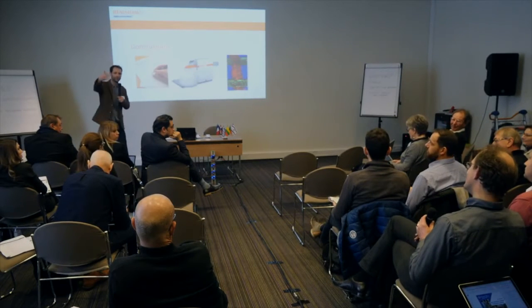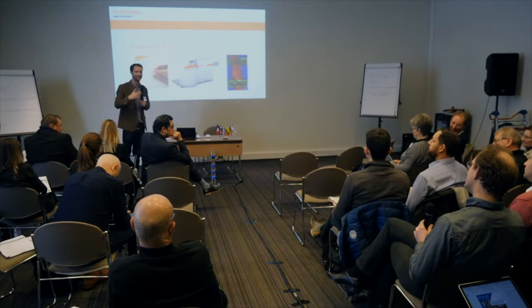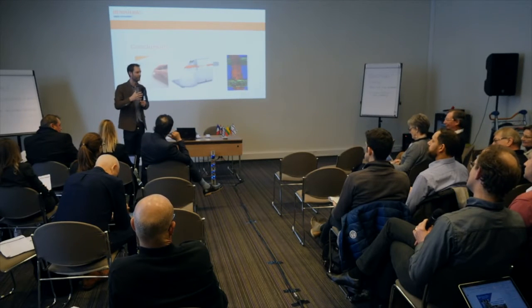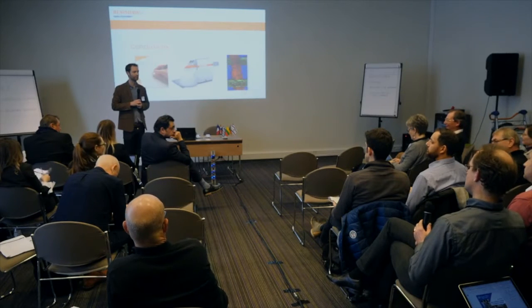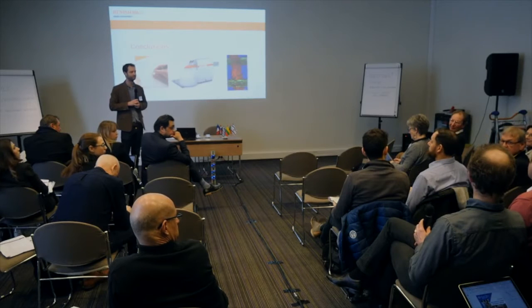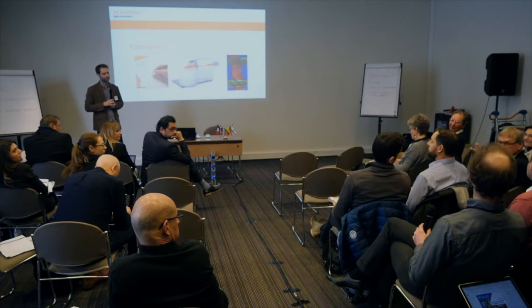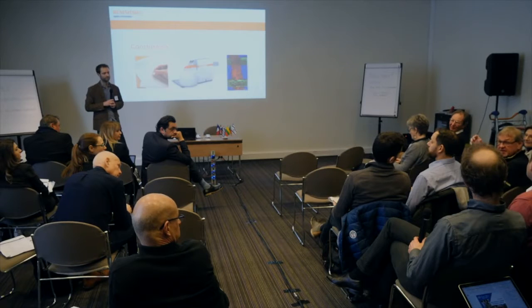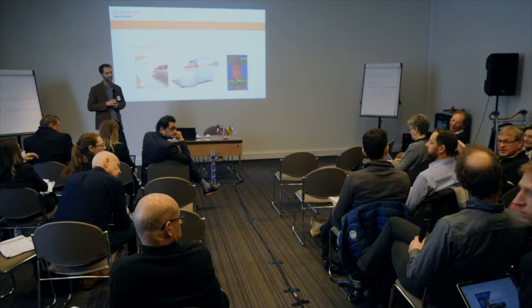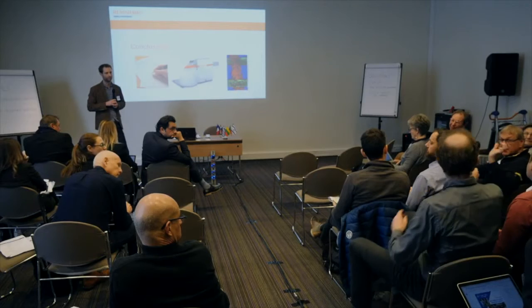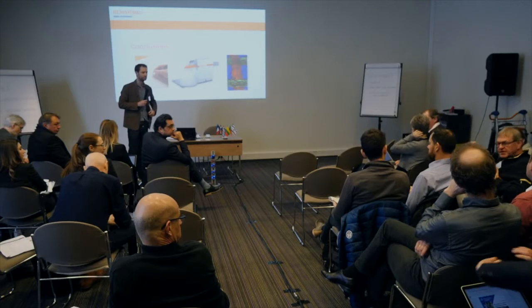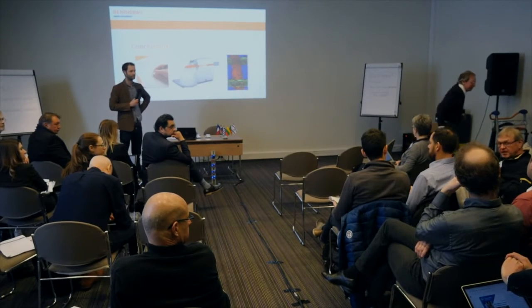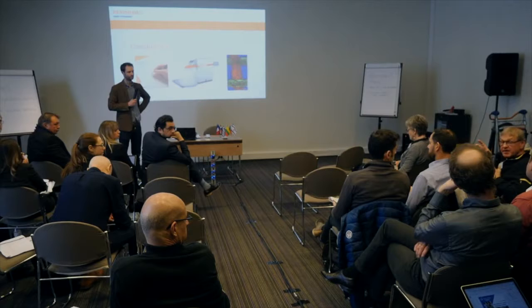Challenging. Yeah. So it's not so much about the travel time, it's more about the specification of it, in terms of repeatability and resolution. There's still a stage on the market, 30 by 30 centimeters, but it's exactly what you said, the precision at the ends is decreasing. Yep. The values given by the producers are mainly dedicated to the middle, and the more you come to the outer areas, the more the precision is lost.